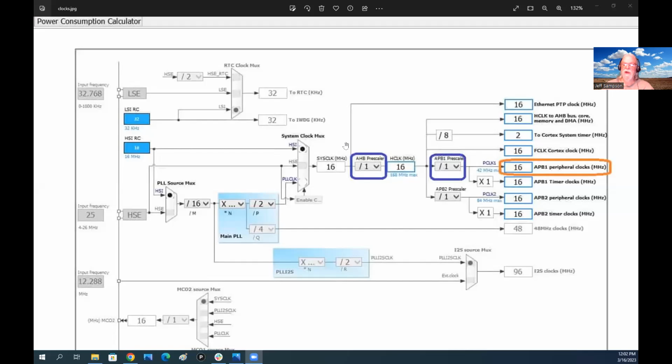Okay, assuming you can see that, that's the clock structure on an ARM processor. It's quite an elaborate thing. On the left here, right now it's not set up for the external crystals, but on my board I've got a 32 kHz crystal for the real-time clock, and a 25 megahertz crystal for the main clock. The Blue Pill has an 8 megahertz crystal. So you have to put the correct crystal frequency here, and click on this to enable the external crystal.